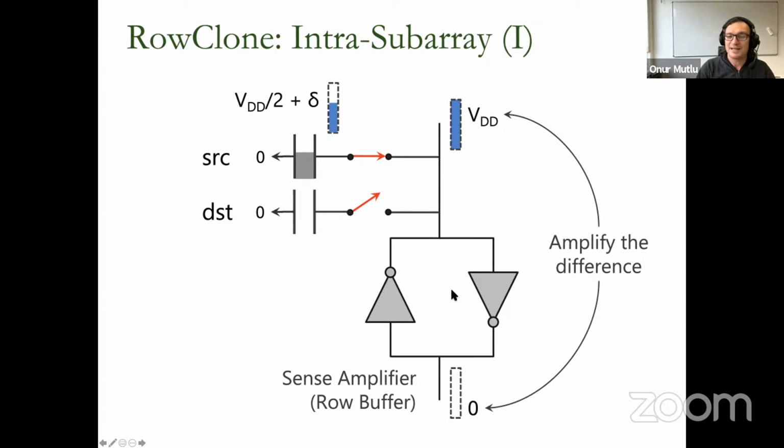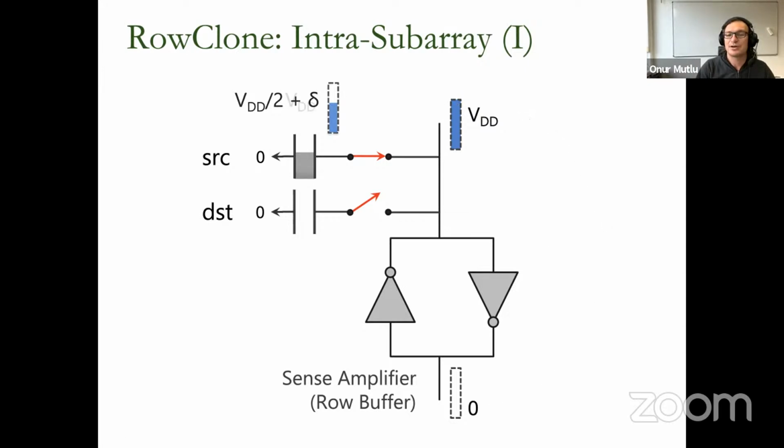Now the next step in activation is really restoring the charge. Because of charge sharing, the sense amplifier is very strong. It's huge, actually, compared to each of these cells. As a result, it drives the charge back into the capacitor, so the capacitor gets replenished with full charge. All of this becomes VDD in the end, because the initial starting point of the source cell was VDD, meaning a charged state. Okay, we've captured the data in the sense amplifier now, as well as the bit line.